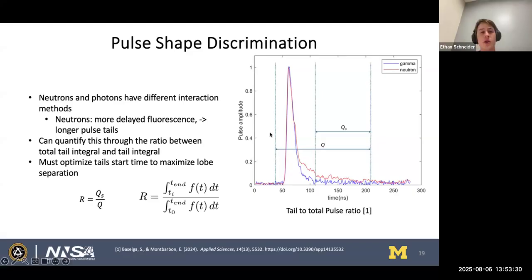Yeah, so one thing that you do whenever doing this kind of processing is that you do cleaning of your data. So here on the right are pulses that are very clean. It's a single pulse, so we have that clean amplitude in our tail. This is not going to be the case with all your data that you get from a system. In some cases, you're just going to get a single noise pulse, and that's all you get. Small pulse, that's it, and you'd have to remove those pulses.